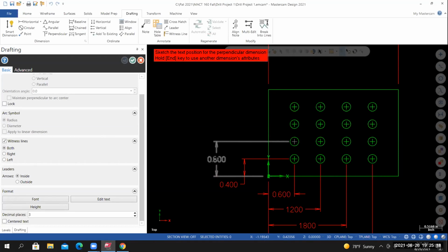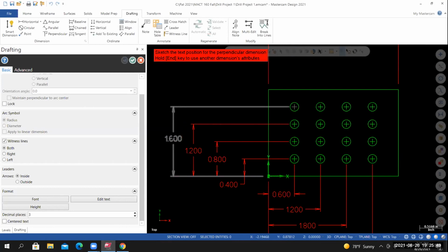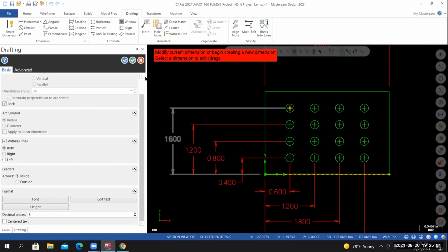If you're not selecting create new operation in between, you're just clicking away, is that okay? If it works, it's good. Yeah, there are some steps that you can skip. What Brian is referring to is, I didn't click the OK create new operation icon. If I just select the horizontal line and just keep working my way through it, that works also. And if you watch my videos, I don't hit that between creating each dimension.